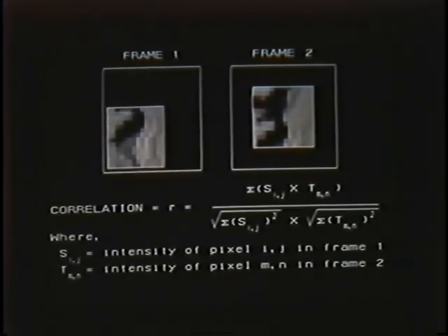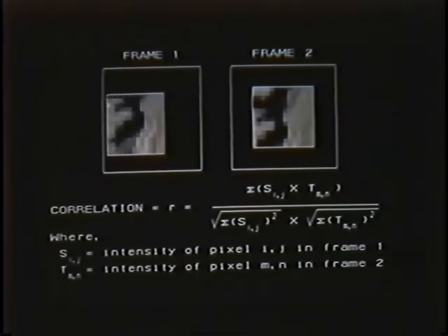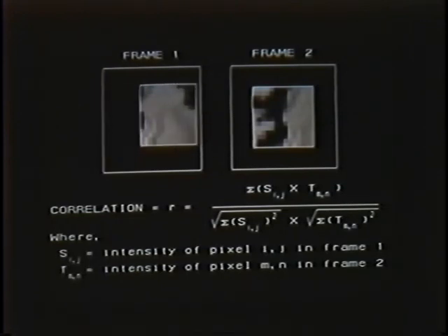Our goal is to find the best match. This will tell us our estimated multi-pixel shift to the nearest whole pixel. The correlation function, which we will identify with a lowercase r, is used to determine the best match after each shift of the window. As a result, this method for estimating multi-pixel jitter is known as shift and correlate.